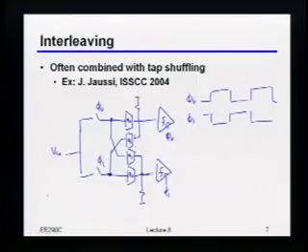So as an example, in the linear equalizers, that tends to be a little bit trickier because setting gains precisely is kind of tricky. But for example, in the DFE, if I had 2 current steering DACs, and those are really largely DC DACs, I can probably design them to match sufficiently well that I wouldn't necessarily have to adapt them individually. Maybe. Key difference being that's outside of the signal path versus this is all the high-speed stuff in the signal path. And so making it match that precisely is probably expensive from a power standpoint. It's a great question. Other questions on this?